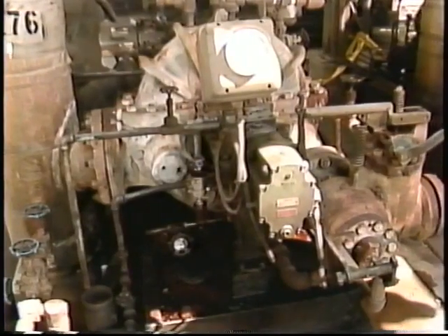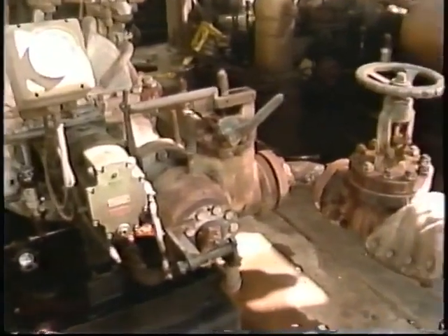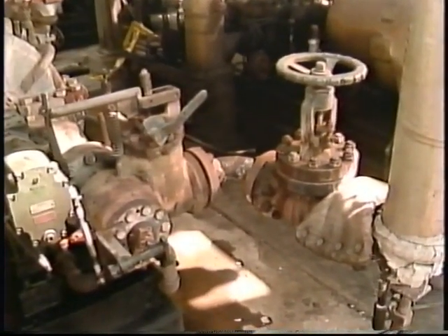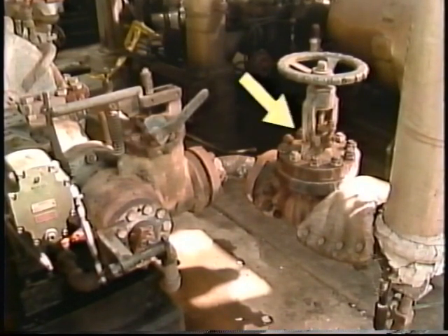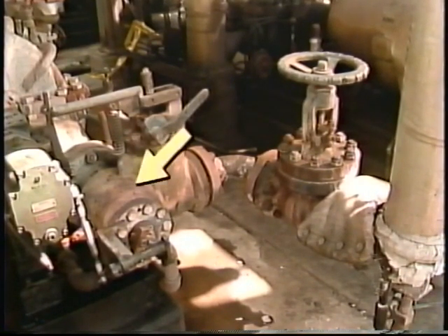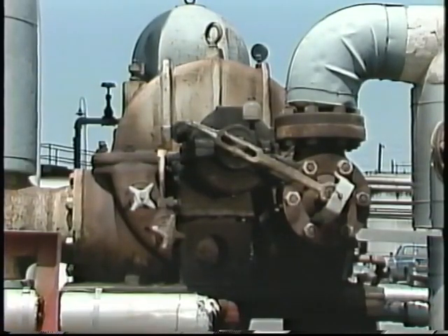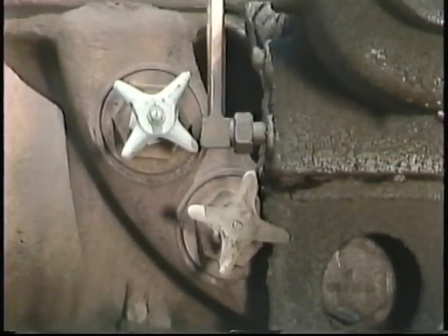Also, for the turbine to operate properly, the steam flow through the turbine must be regulated. Two major valves that are used for this purpose are the throttle valve and the governor valve, which we've already mentioned. Some turbines also have nozzles that are operated by external hand valves. The hand valves allow individual nozzles to be selected in or out of service manually for better efficiency during certain situations, like startup or a change in load.